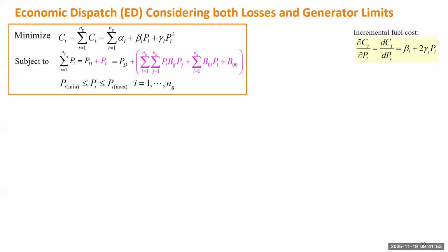So let's quickly go over what we have concluded so far. For the cost of each generator, if we calculate the derivative with respect to the output of that unit, that gives us the incremental cost, right? This is because the cost we have considered is a nonlinear function in quadratic form, which makes the incremental cost for each unit a linear function. So this is the straight line in our graph. We have many straight lines of different slopes and different ends.